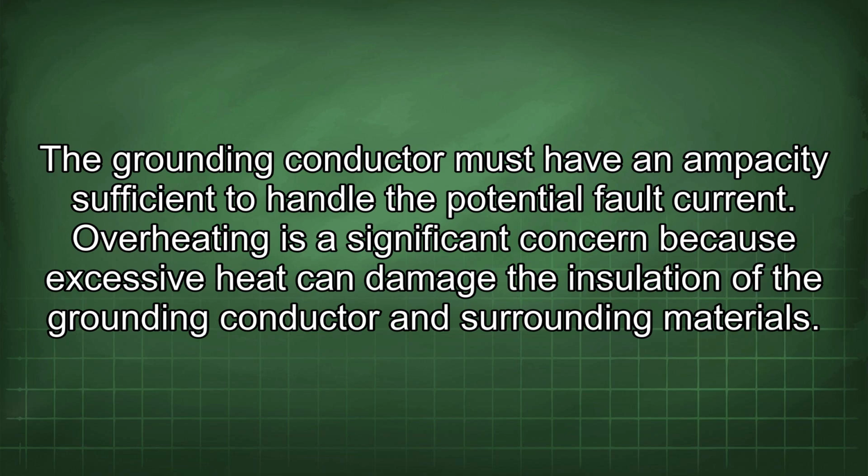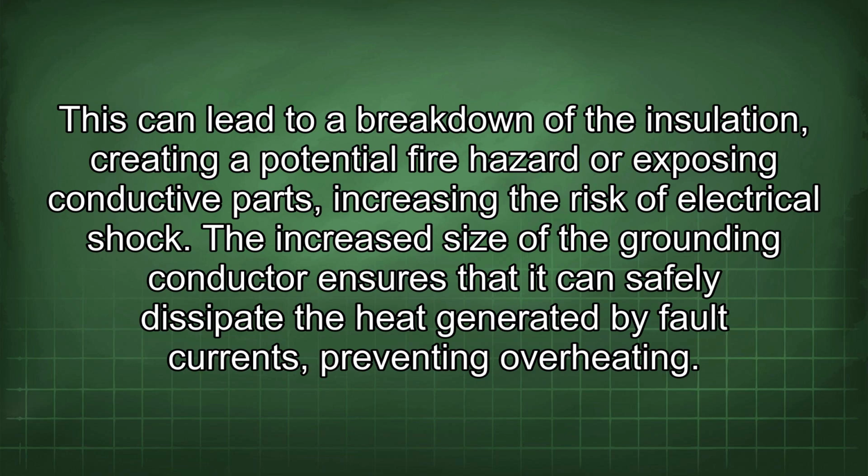Overheating is a significant concern because excessive heat can damage the insulation of the grounding conductor and surrounding materials. This can lead to a breakdown of the insulation, creating a potential fire hazard or exposing conductive parts, increasing the risk of electrical shock. The increased size of the grounding conductor ensures that it can safely dissipate the heat generated by fault currents, preventing overheating.